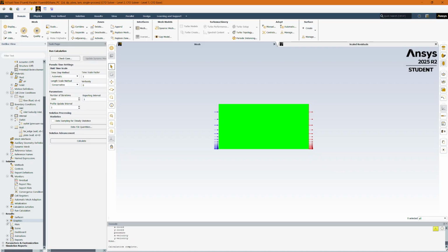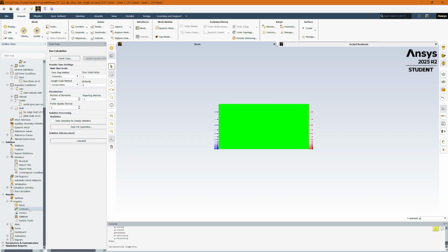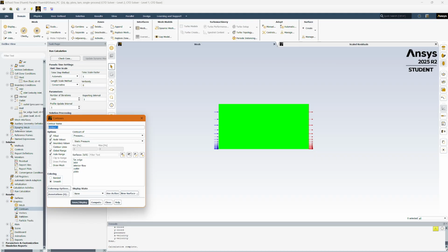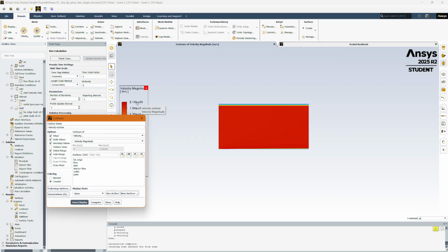Okay. Now we can start looking at graphics. So, start with velocity. And we can see that this is the top wall, not really what we care about, but we can see very normal, undisturbed flow with max magnitudes up here. So actually what we're seeing is a maximum velocity of 2.15, which is above our initial velocity.